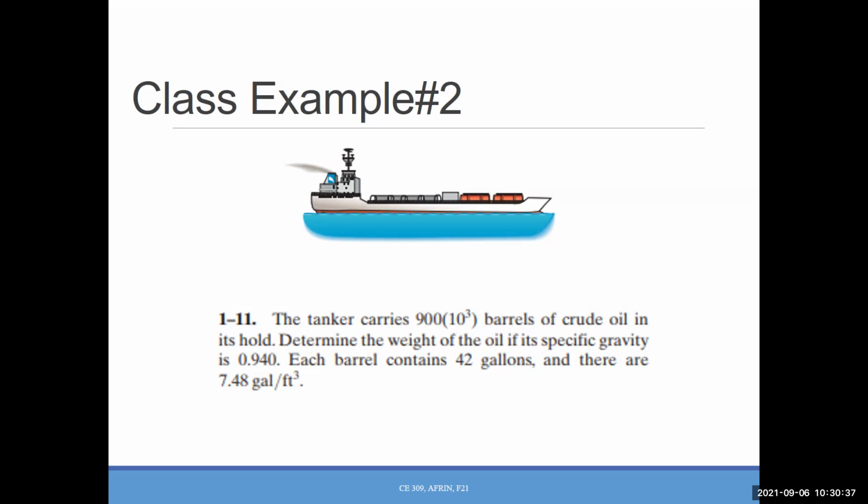Now you can see we know the gamma oil, and we can connect that to here, right? Okay, let's do that. So from equation 1, can you read my handwriting on the board? The last row? Okay. So W equals 58.65 pounds per feet cube times the total volume. What is the best way to find the volume? We know the number of gallons, right? What is that? This one, 42. So 42.